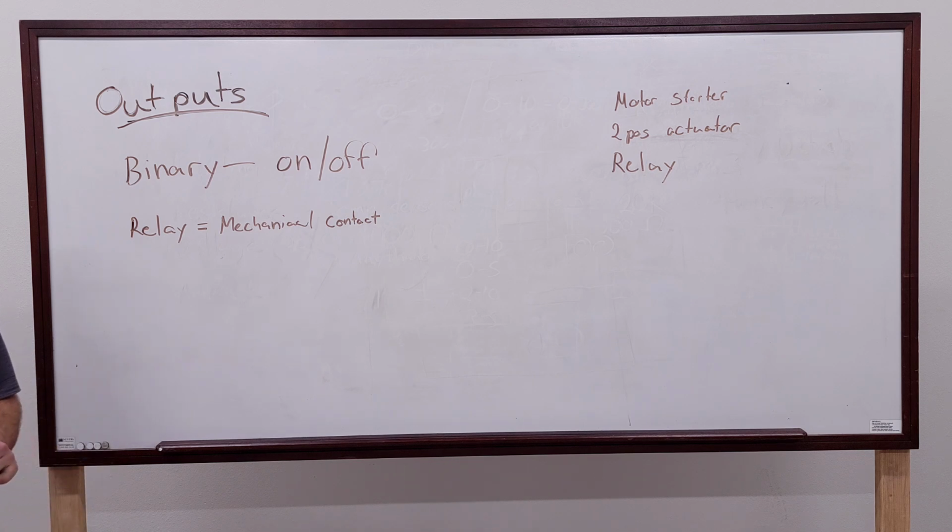And this is not to say isolation relays are the end-all be-all, because they can still blow up too. But it is a $15 relay cube versus a $400 controller. I'd rather take the risk of popping a $15 relay cube. Usually the bases make it. It's the cubes that don't, because they have these little bitty 22 gauge wires inside of them that just can't hold any amperage. They heat up, they burn up, then it arcs, and the whole thing's toast.